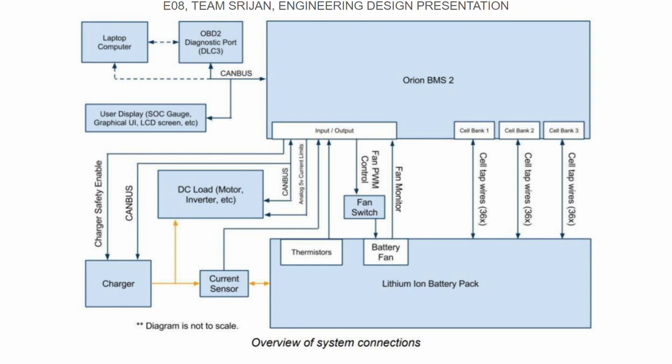The data logging display module connects to Orion BMS via CAN bus, enabling data logging to an onboard SD card and displaying state of charge through an internal LED bar graph. Meanwhile, the Orion BMS Connect's Wi-Fi module facilitates data logging to an SD card and transmits data to the Orion Connect cloud servers via Wi-Fi, enabling remote data access with an internet connection.